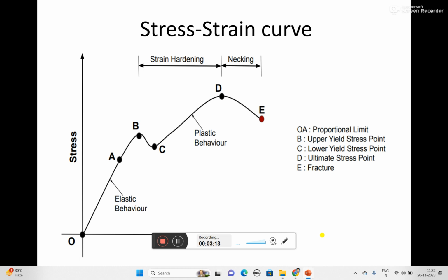Mainly, we know what stress is. Mathematically, stress is represented by resisting force per unit area. Whenever a load or external force is applied over a body, the inside molecules of the material will resist that applied external force. Due to that, it will develop an equal and opposite resistance force that opposes the applied external force, and this develops stress in the particular material or product.